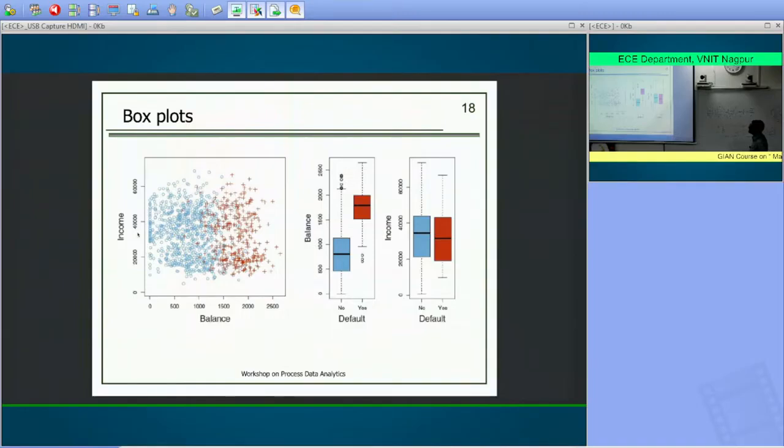This is an interesting plot. It's called a high-density alarm plot. On the x-axis, you have time, and on the y-axis, you have various alarms. And you're counting the number of alarms on each day. If you have 0 alarms, then you don't show anything. If you have lots of alarms, you show it with those red bars.